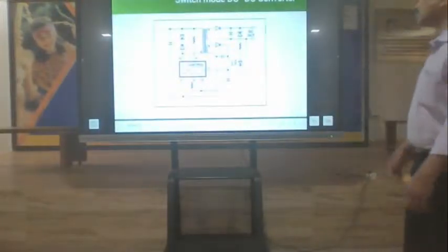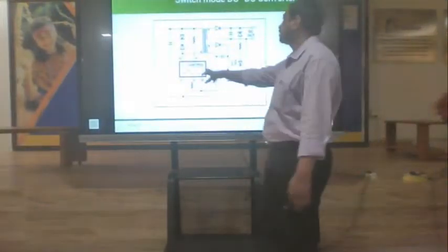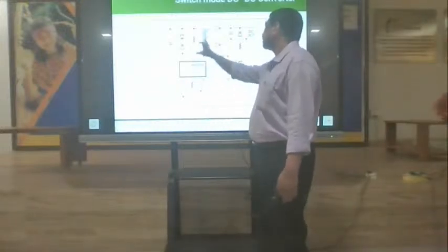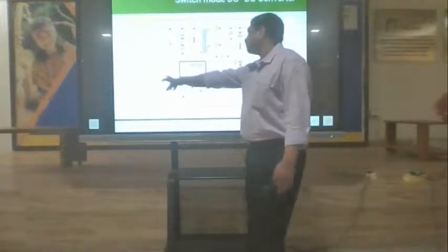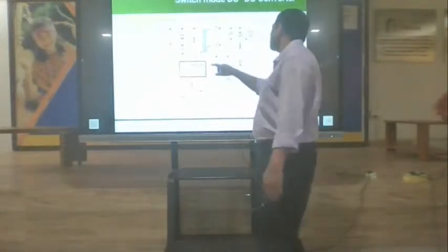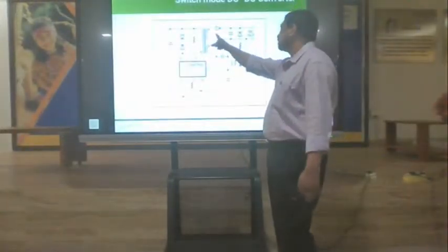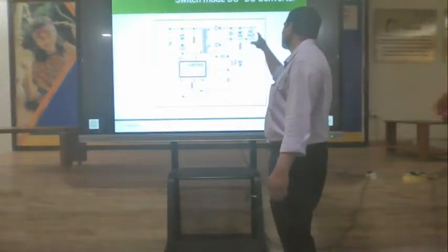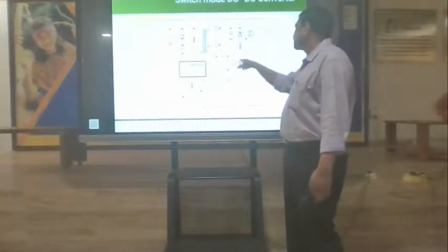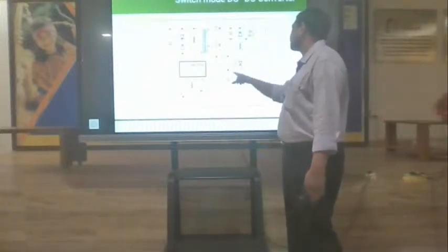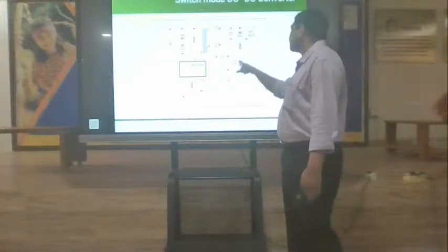So this is a controller. You have a controller and you have a transformer. This controller will switch this transformer on and off. You have the input DC supply, and this is the output rectifier, and then you get an output supply. This output supply is sampled through a feedback network where we have a V reference.